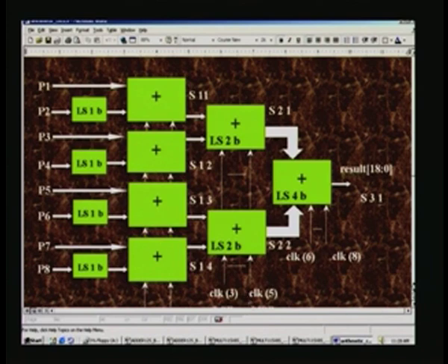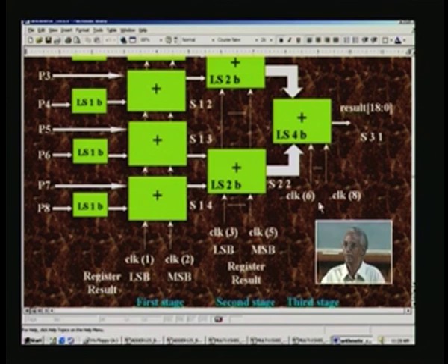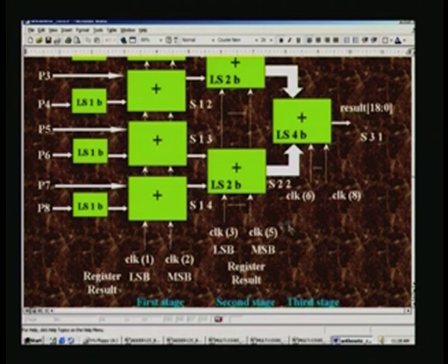You can experiment with this to see whether we can reduce the clock, and there may be some scope for you to reduce. Instead of 8 pipelines you may get even 6. In fact this is not really required, because what we are going to do is pipeline not only the multiplier but also the entire process. Even a complicated algorithm can be pipelined totally, and all these pipeline delays will only be a one-time affair.